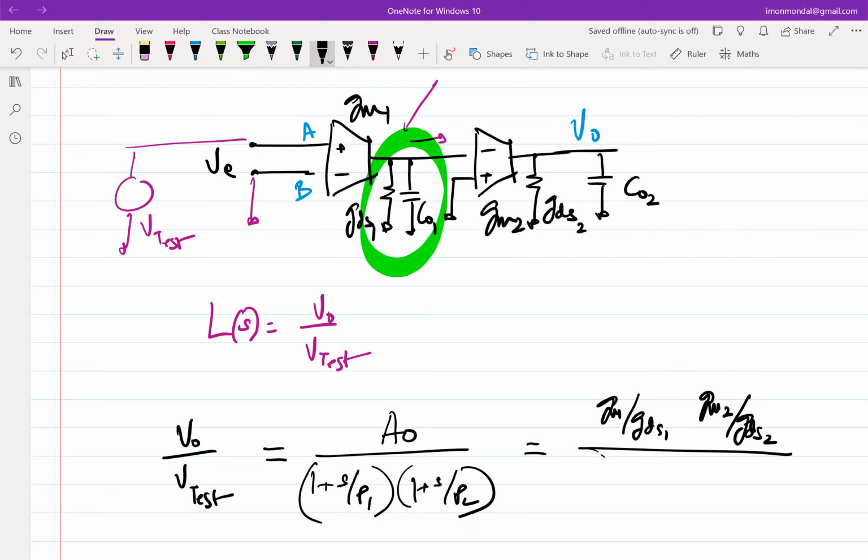So what is the time constant associated with that highlighted node? RDS1 times C01. Yeah, so which means that the pole associated with it, 1 over the time constant, is GDS1 by C01. So 1 plus S by GDS1 by C01 times 1 plus S by...